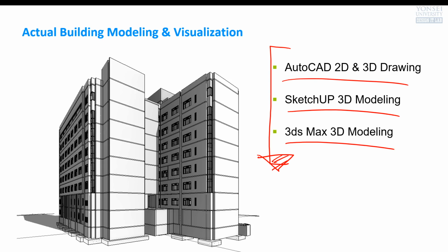We have an object-based building information modeling approach. Why do we use this? In this project, Revit is a good tool, but as I told you before, if you're in charge of early phase design visualization, quick visualization using surface-based modeling, photorealistic render, or concept visualization, in that sense Revit is heavyweight. You don't need it. What you need is SketchUp, 3D Max, Rhino, whatever. Surface-based 3D, okay? That's why we still need those tools.